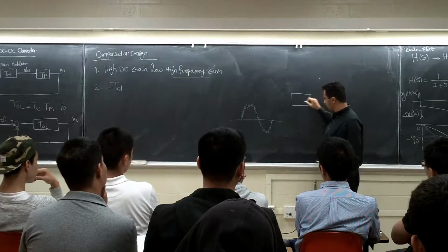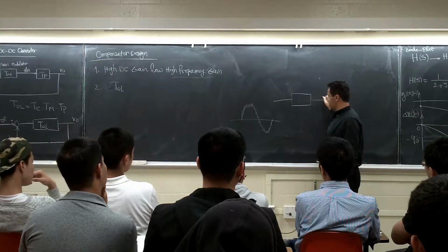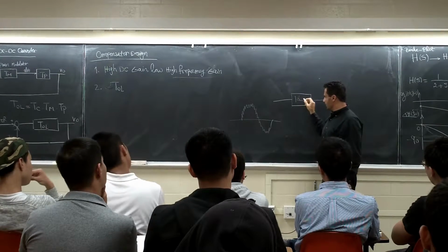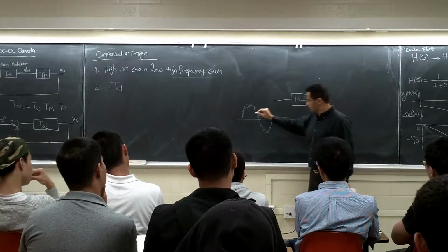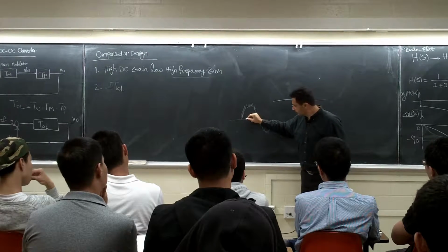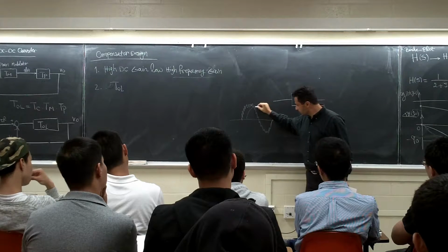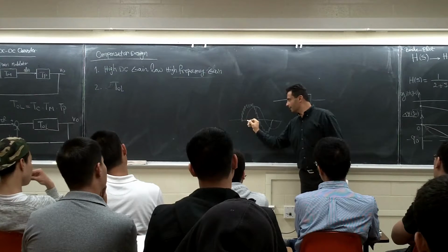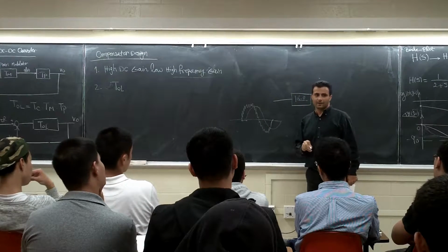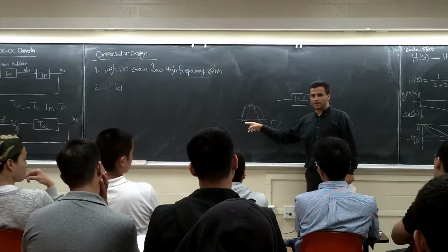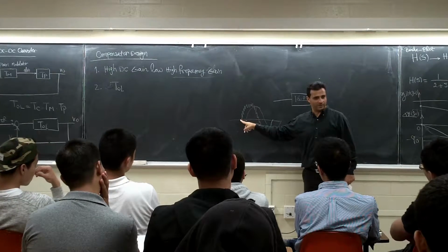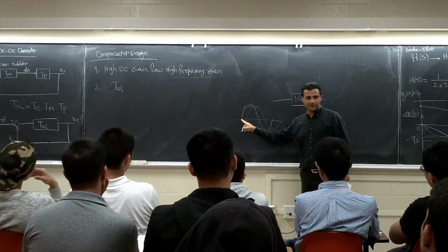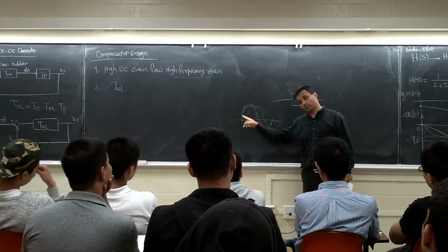Every filter you can look at as a complex number. Let's say the gain is designed to be 1, but there is some angle here. I'm exaggerating it here. The signal is going to be like this, this is a filtered signal. There's going to be a little lag. It's going to reduce the phase margin. But the problem here is that this is not the real signal I have in my system. I cleaned up my signal, it's better now, but it's shifted. Believe me, this one is causing us lots of problems.